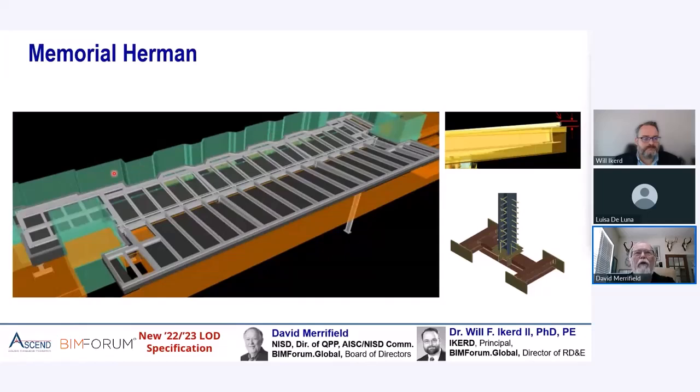So when I first looked at this, I realized that with all the different elements and how this had to go together, we could detail it and fabricate it, but it wouldn't necessarily fit the building. Yeah, you get it just precise. It just may not be accurate. So in fact, when I first looked at this thing, I decided that laser scanning the building and the different elements that were in place was the first step before we could ever start to even model it.